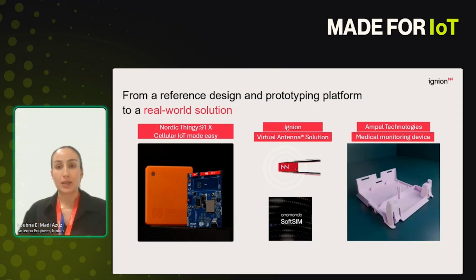For instance, imagine the LTE antenna covering certain bands, and 6 months later, those requirements change to different bands. In this case, from the antenna perspective, we could just shift the antenna response by modifying the matching network. That will be super easy, but we need to make sure that the radio supports this change, the software, and so on. So at the end, we have this trade-off between our solution and the ecosystem, of course.